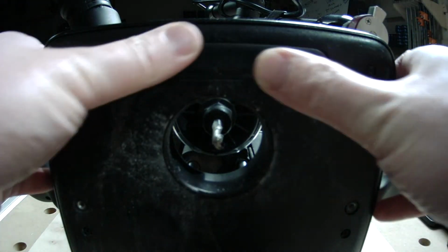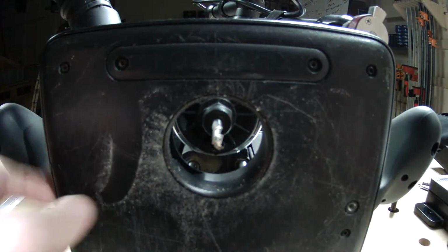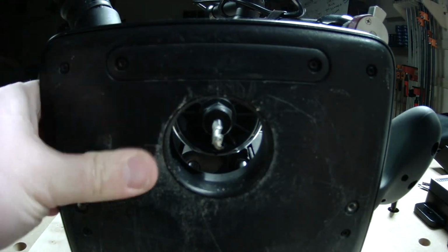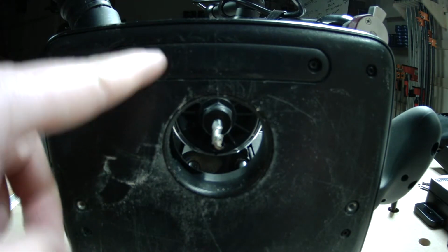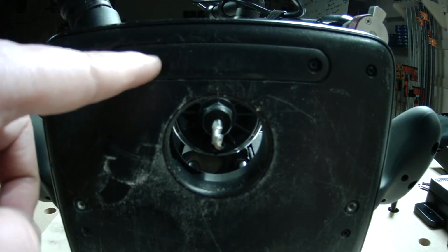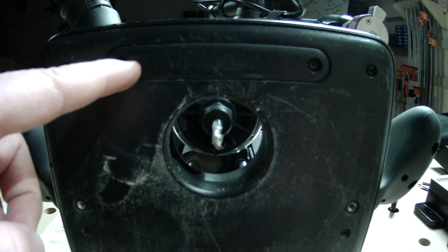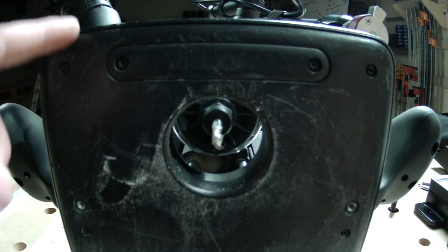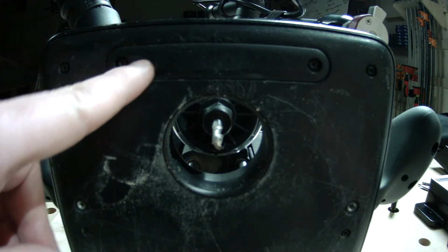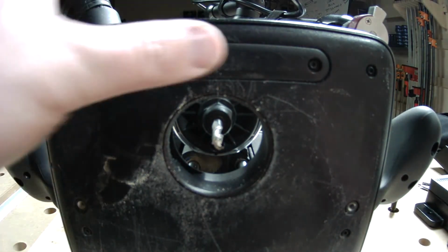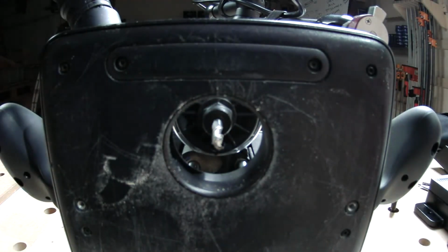It's this little bar on the bottom of Origin. And normally that's just riding happily on a piece of plywood or whatever you're working on. But if this bar isn't on a surface, any surface really, not necessarily the surface you're touching off on, touch off is not going to work. So this bar has to be in contact with what you're working on.